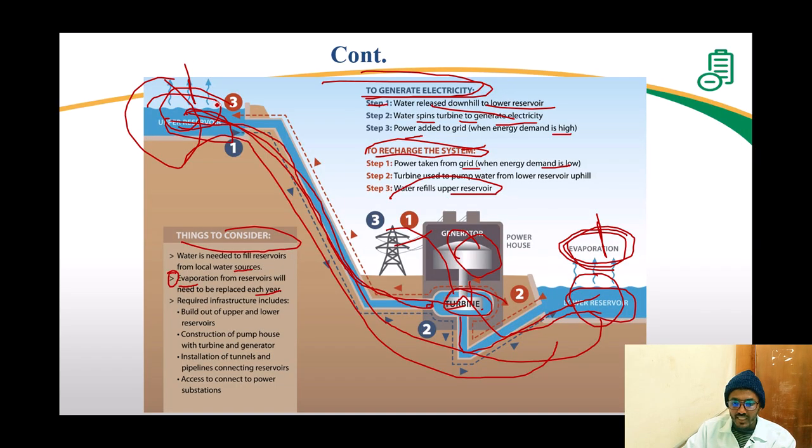As you can see here, we have potential energy, right? And the same thing here, we have this energy. As it goes like this, it is going to convert into kinetic energy. So if this one is higher, there's going to be high potential energy, which means there is high power output. But if this reservoir is at a lower position, this means that we're going to have lower power output. So the reservoir level also affects the efficiency of the hydropower.